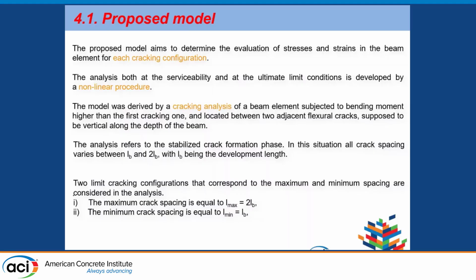The block model was derived by a cracking analysis of a beam subjected to a bending moment higher than the first cracking one, and located between two flexural cracks which are supposed to be vertical. The analysis referred to the stabilized crack formation phase. In this situation, the crack spacing varies between LB and 2LB, with LB being the development length.